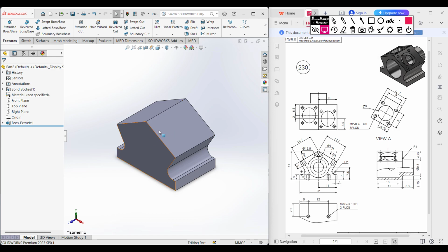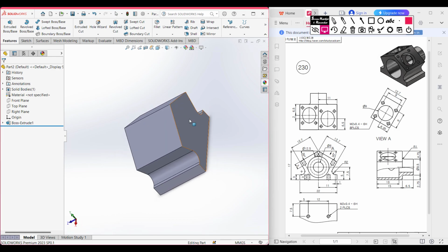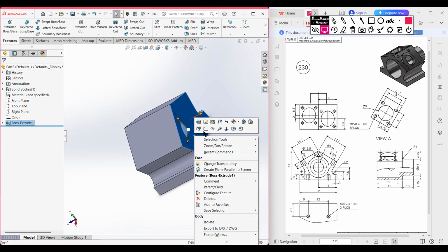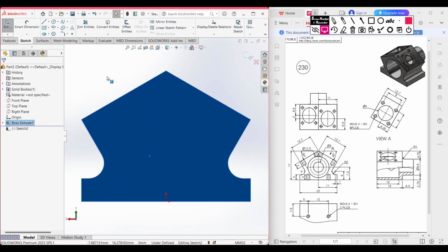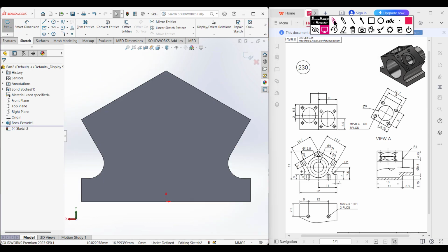Now I'm rotating here and selecting this face, the back face. Now I'll click on it. Now sketch, now normal to it. Before selecting the circle, let me show another dimension. All of our circle origins are 7.5 unit apart from this horizontal line.